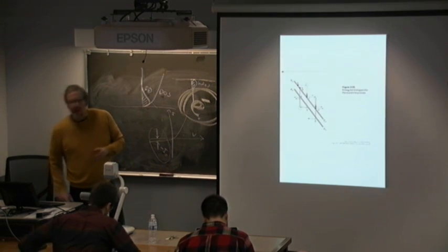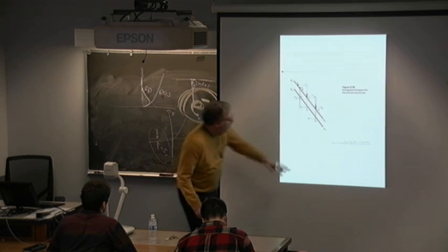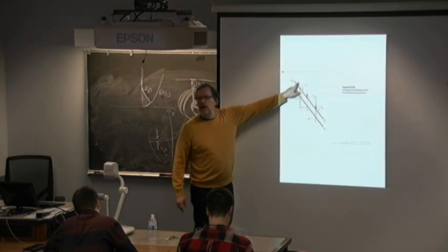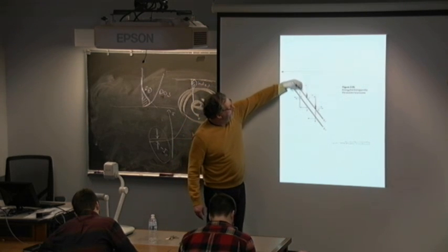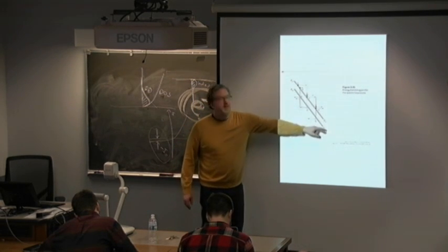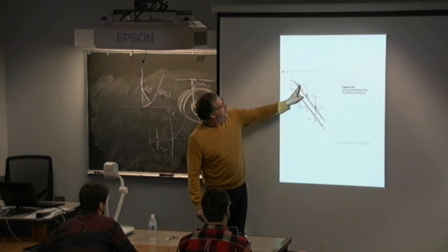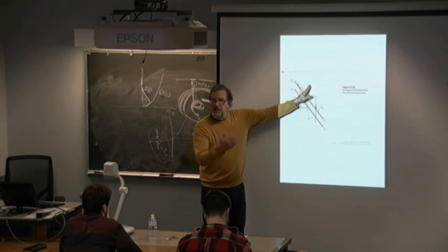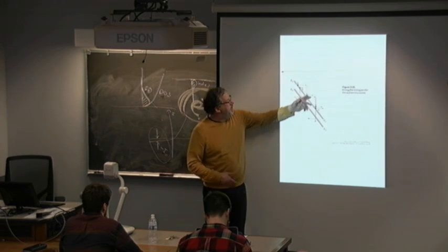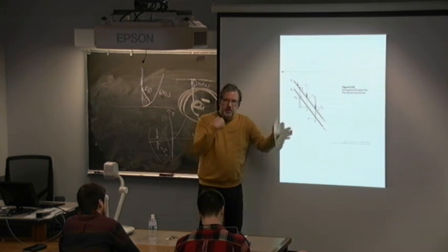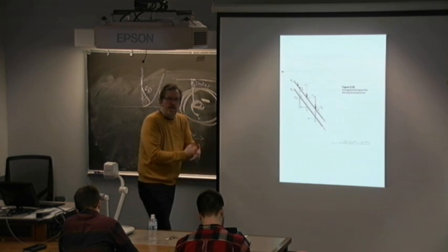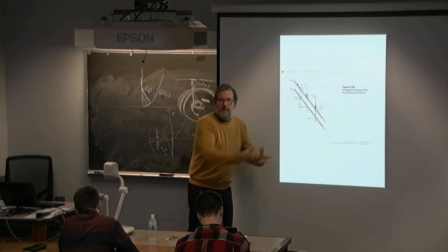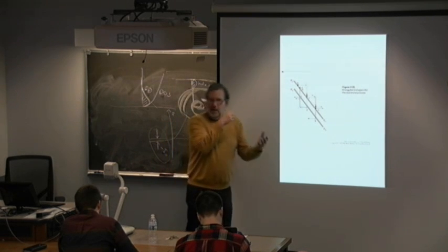Now this is probably good. This is out of little z. This is showing that bowling ball analogy, where it's like ping, ping, ping as it's going down the steps. Here you can see the potential energy turning into kinetic energy, accelerating the carriers, and then it hits a scattering. When it scatters, by conservation of momentum, the carrier imparts all that energy and momentum to the lattice, sometimes causing an electron hole pair.